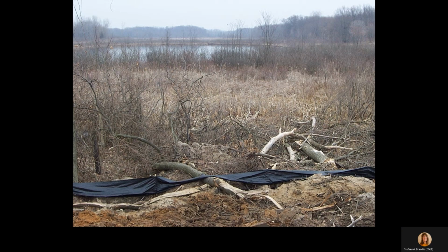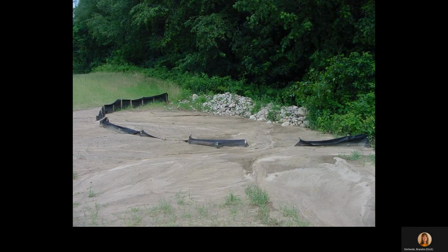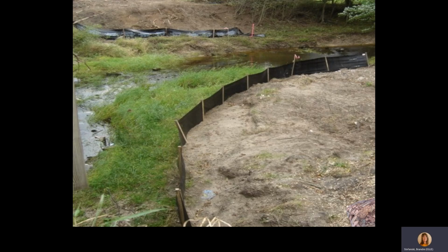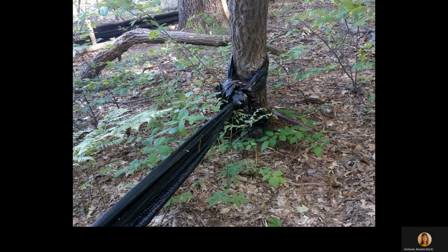Clearly, the silt fence is not preventing sedimentation from occurring. This is a picture of deposition at the bottom of a hill. The erosion controls on site must not have been very good because a lot of sediment has deposited, enough that the silt fence was overwhelmed in several areas. The silt fence in the foreground looks good. What about the silt fence in the background? This technique for starting a course of silt fence is not recommended.